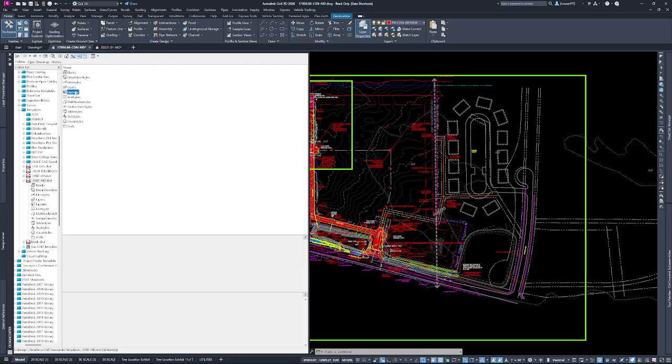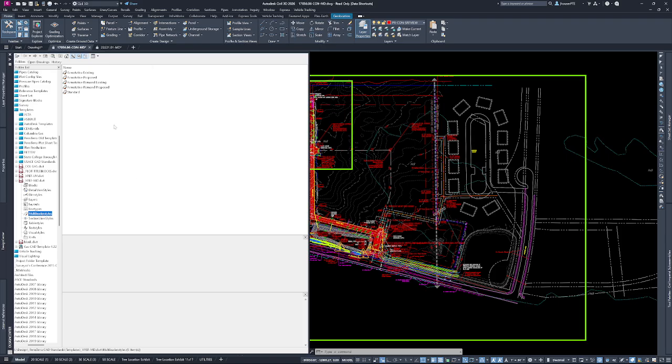This works pretty well when you have multiple layers across the bottom that you need to bring in to another drawing. Don't always get the right viewport configurations, but it brings it all over. Line types are there. Multi-leaders is another one that gets used quite a bit. Or you get a drawing from somebody else and you need to bring these things in. This is a good way to do it.